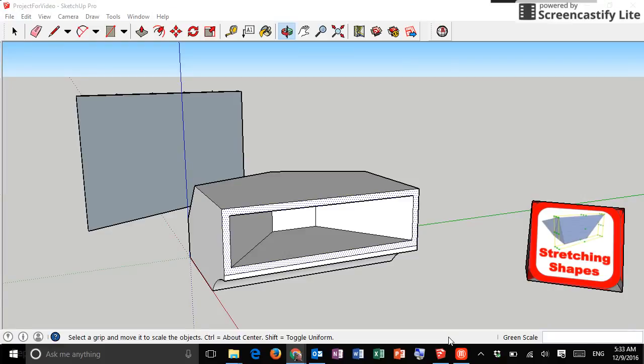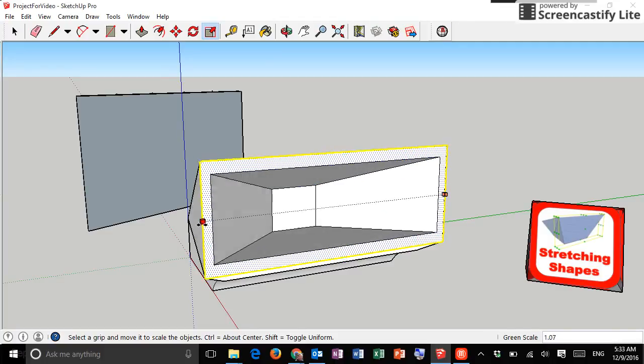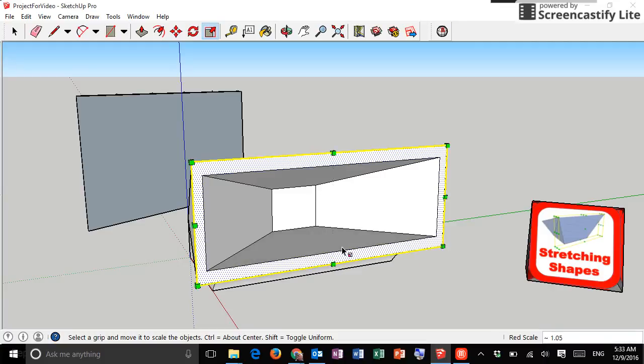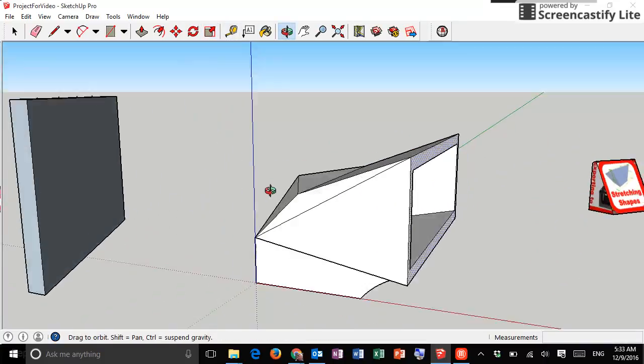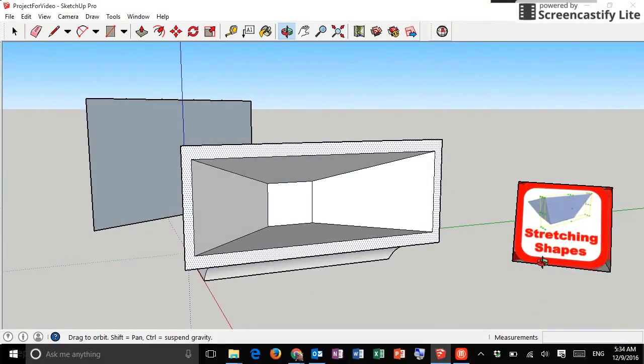There may be times you need to do something much more drastic. You have the basic shape, but it's not quite exactly what you want. So there's a tool called Scale that allows you to stretch existing shapes and distort them in any way you need to. First, I'll select the side. There we go. And click this, grab here and stretch in the direction I need. And now it's a much different shape than it started out. To find more about stretching using scale, click here.